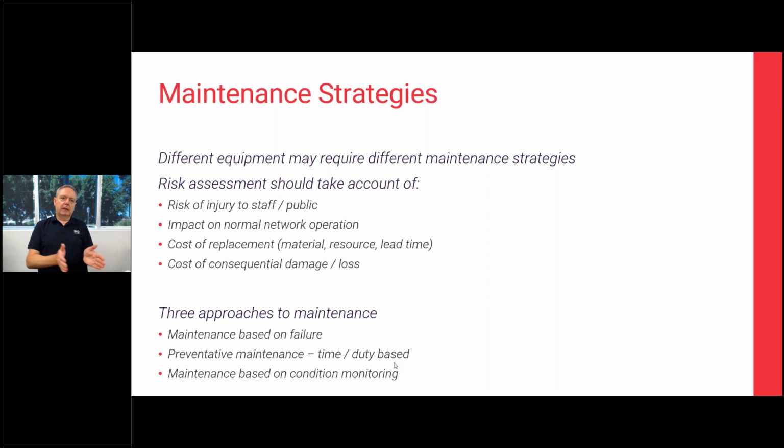Where we've got industrial situations where we only have periodic outage availability, then it can become a mixture of those bottom two. So we will carry out condition monitoring, and based on the results of that, we will then target the maintenance in a specific time. So that is really the way that we like to run networks where we've got specific outages.